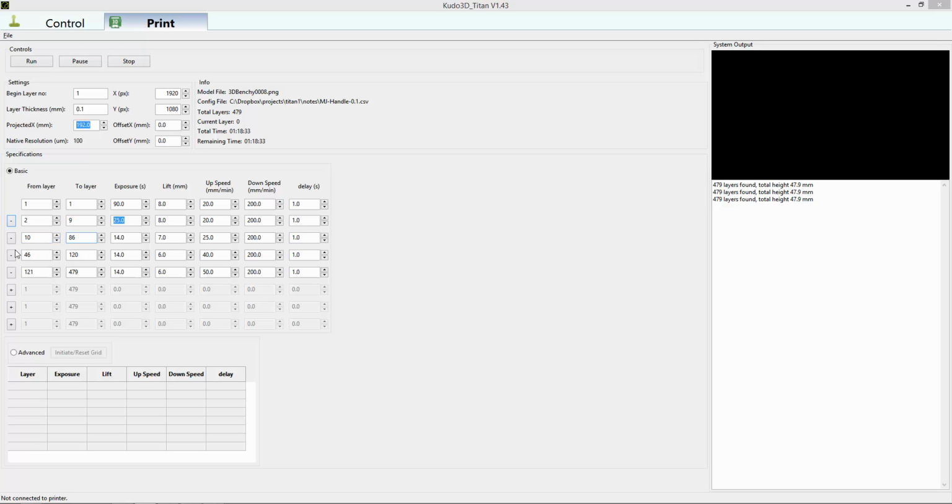with bigger and slower lifts. Stay at 7 seconds and then lift more slowly. I'm going to actually be relatively conservative, and so I will dial down these numbers all the way up just to make sure that I don't have something break off. Having conservative lift speed is important because we don't want to lift too fast and then have something break off, either lift up our FEP film or have the part fall off. So we'll go 14, 14, 14, all the way up here.